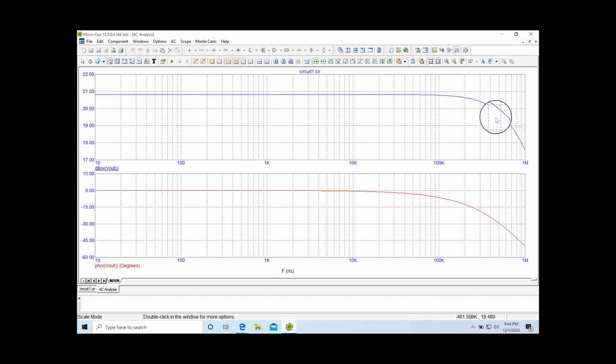And the reason it rolls off is because that's the op-amp going to roll off. It's going to be gain of 0 somewhere out here, 1 or 10 meg or whatever. This guy might be a 5 meg op-amp, pretty fast op-amp. But yeah, he's rolling off because of his own internal structure. All right, guys, I think that kind of helps you get into the op-amp stuff, right?